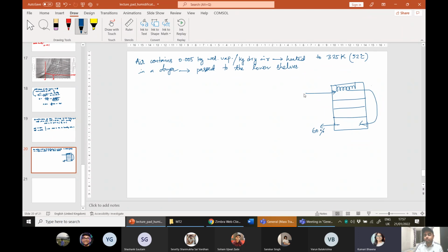right? So humidity content, this obviously means the air that you are introducing into the heater, or leaving from the heater, is much lower than 60%, and essentially here you have some wet solids, right? Here you have some wet solids which need to be dried using dried air. So in the process, air gets humidified and the solids become dried. Once you dry them out, the air takes up that moisture and becomes humidified to 60%, right?